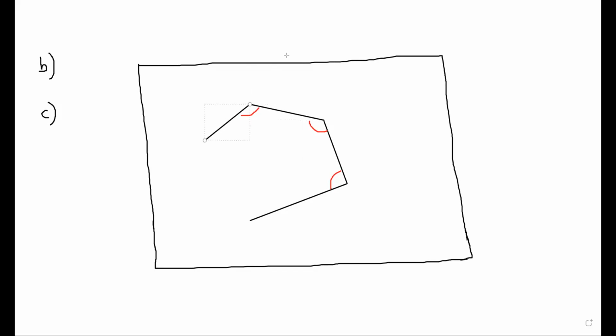At the end, what will happen? This is the important thing. At the end, when you mark the last angle and the last length, you will end up with an unclosed polygon. It can go somewhere the other way also. It may cross somehow. It may not come to the expected point or the origin.